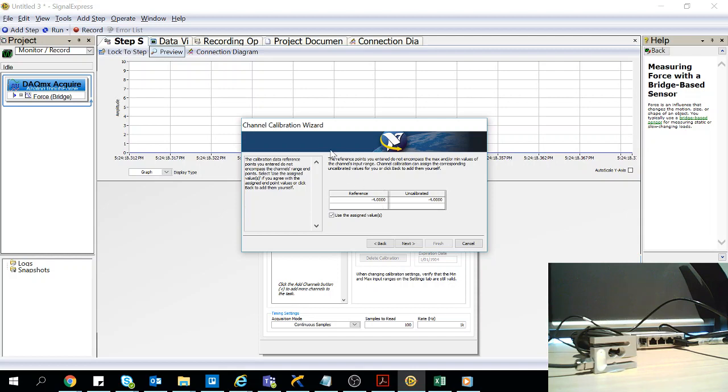The calibrated scale will override your configured scale. But for the range, for example, my configured scale has a range of -4 to +4 kilograms, and I do not have a physical unit to calibrate the -4 tension. So it asks me if I want to use the pre-recorded reference unit, and I say yes.